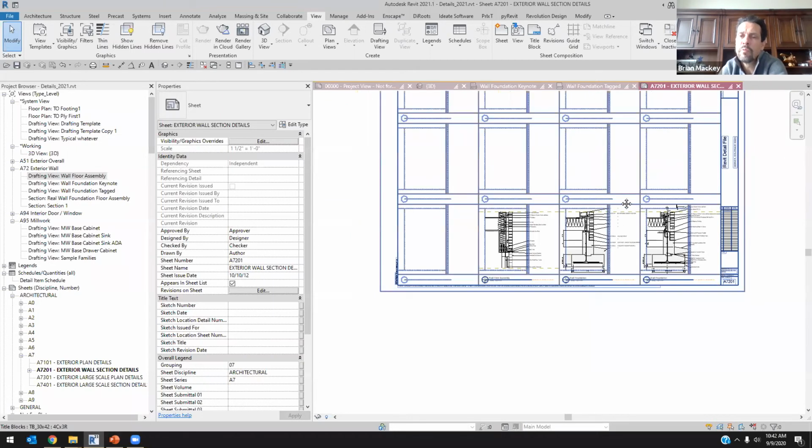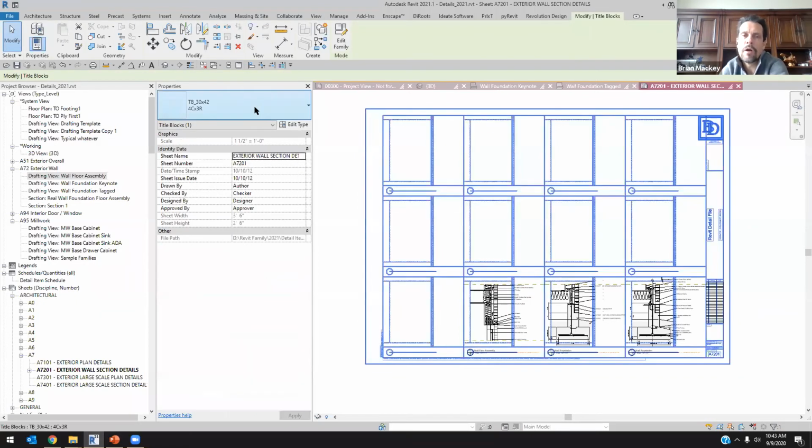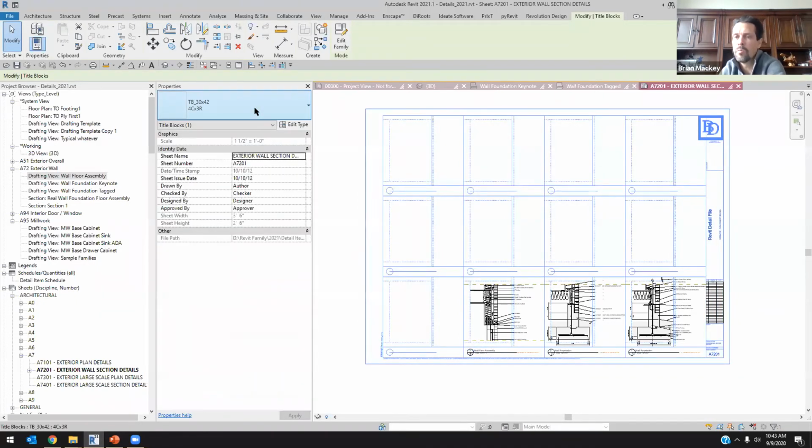Now, the last thing I have when talking about this is all of the families like the title block, etc. These orange lines are going to print. And I know I'm never going to remember to go back and grab this title block and switch it back to the no guide. Somebody's going to go print. You're going to have all this orange stuff all over the place. I did choose orange. It prints a pretty light gray.